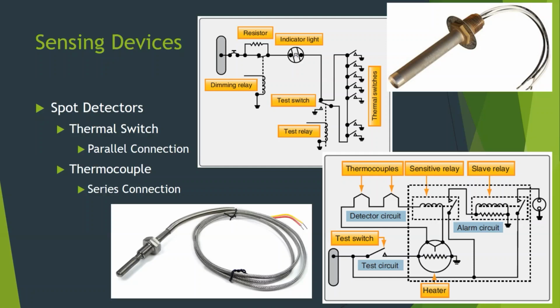But we had no way of knowing where it was, other than you could go and disconnect them at certain spots and see if you could figure out which way it was. So we'd break it between where it entered the pressure bulkhead. We'd break it and, okay, hopefully we see the fault back here in the tail somewhere, because they're a lot easier to get to.